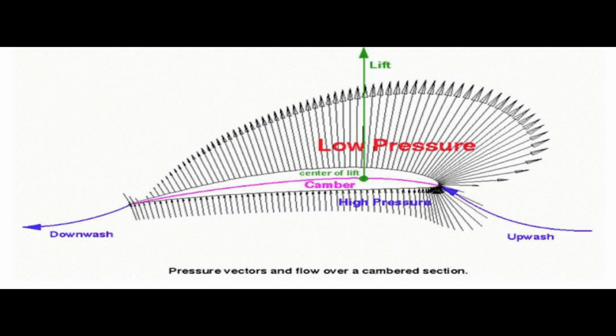In conformance with Bernoulli's principle, where the airflow was slowed beneath the airfoil, a positive upward pressure was created, i.e., as the fluid speed decreases, the pressure must increase. Since the pressure differential between the upper and lower surface of the airfoil increases, total lift increases. Both Bernoulli's principle and Newton's laws are in operation whenever lift is being generated by an airfoil.